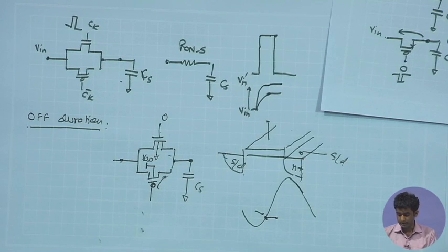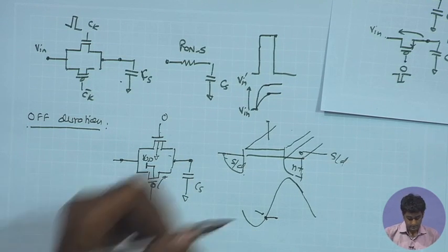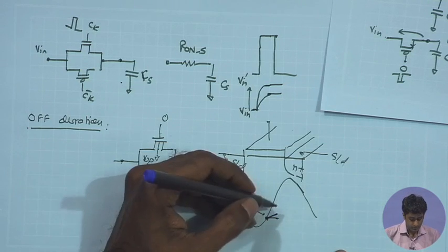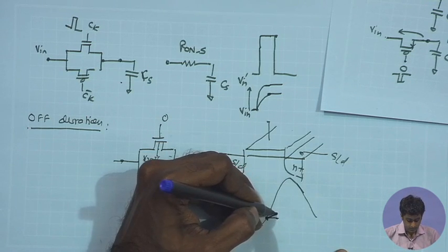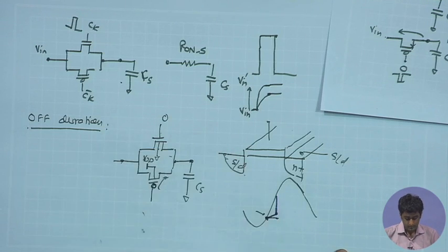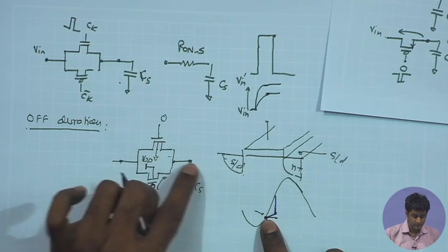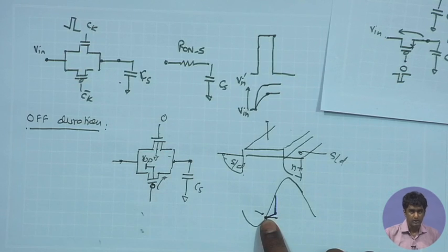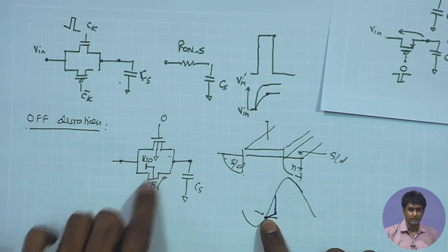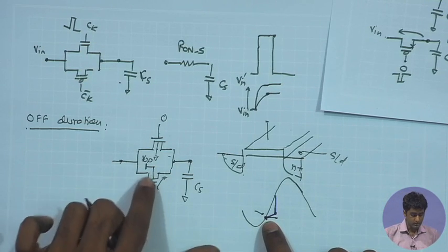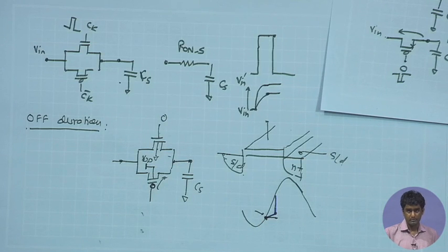So, what we expect here is that you are going to get a slight increase in the sampled voltage, rather than being constant it will show some increase, and then next time when you are putting the switch on, again it will go towards the new value, again depending upon the condition of the switches over here it can show increase or decrease. So, when the input signal is low or the sample value over here is pretty small, close to ground, then the reverse bias junction leakage of the PMOS is going to dominate, and it is going to increase the sample voltage a little bit.